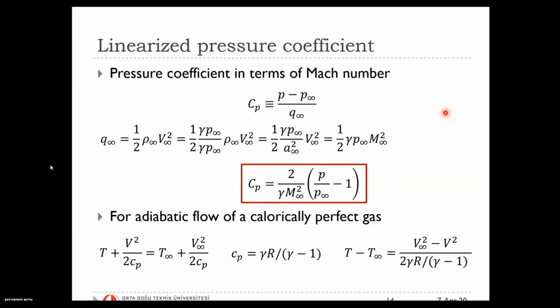Well, after having this equation, there is one other important flow parameter that we may be interested in, because we would like to eventually get lift and moment coefficient applied on the object in the flow, and in order to get that, you may remember from aerodynamics 1 classes, we need to integrate the pressure coefficient. Here the pressure coefficient is defined in a conventional way as static pressure minus static pressure of the free stream flow divided by the dynamic pressure.